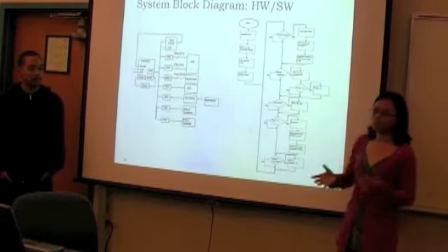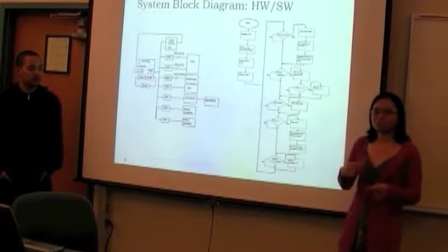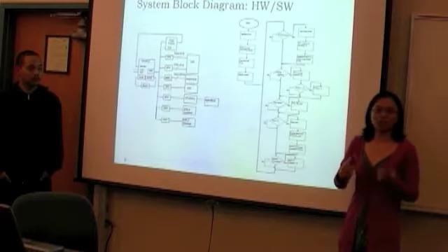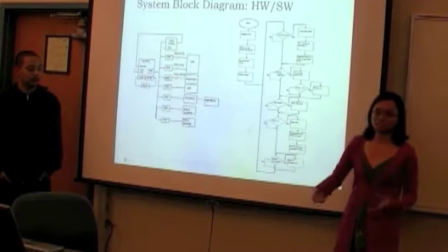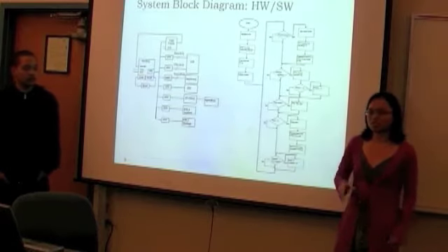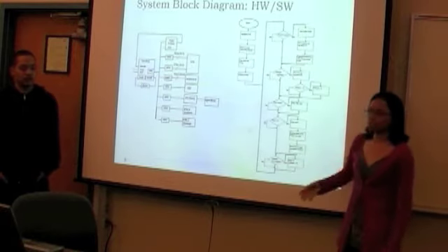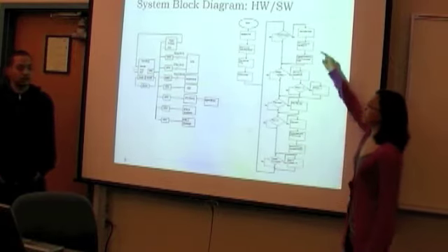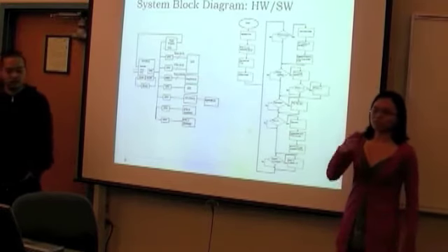So play the note, it will display the note on the LCD, and it will increment this counter, because the counter is used to say how long the note will be played, which comes here, says if the counter has been exceeded for some certain value, it will say flag 0, which means turn off playing the note on the next iteration of the loop, and the counter will go back to 0. So next time if flag was 1, then we know that it will start all over again at 0, so it will count the same amount of time.